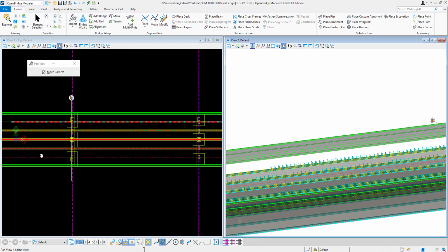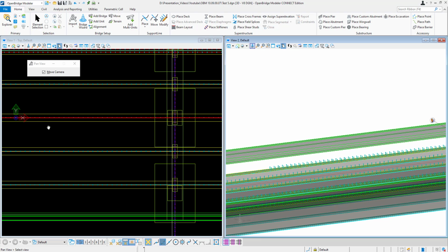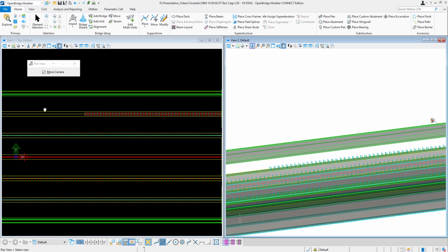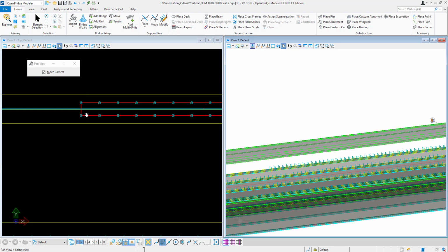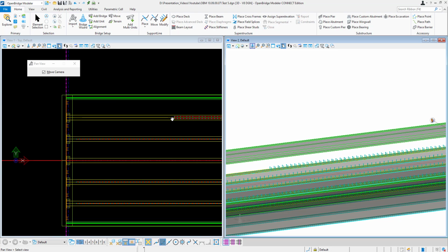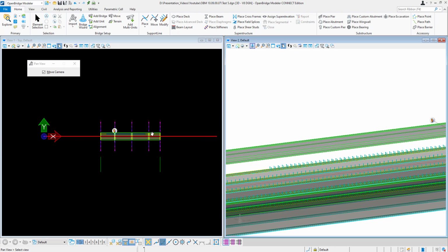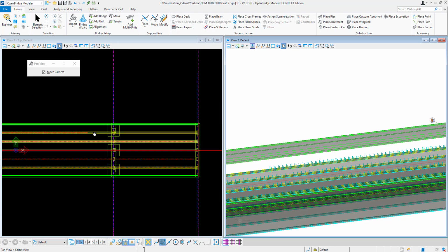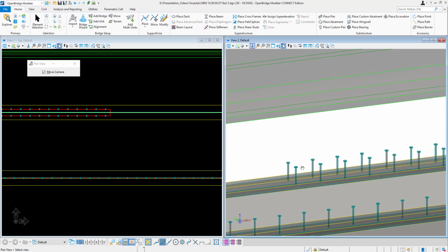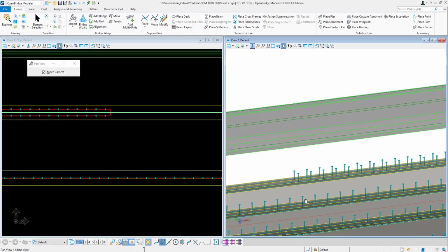We can see the other beams are as they were, but for the left one, the first one on top here, they now have 2 rows, and that has started at 10% and finished at 75%. So, and there are two studs, 2 rows at 300 millimeter, whereas there are only one studs